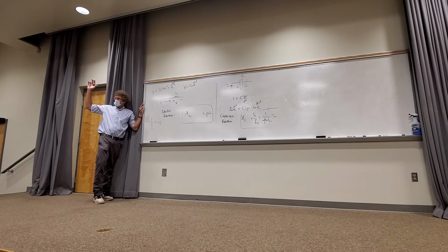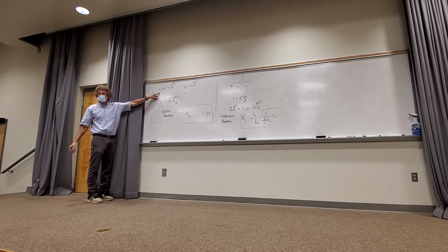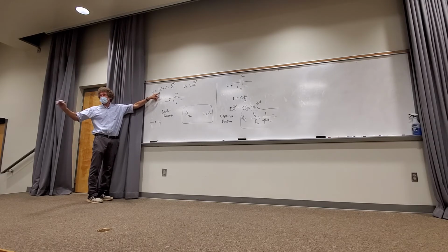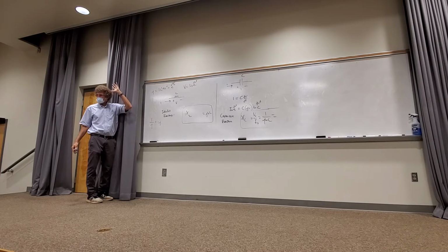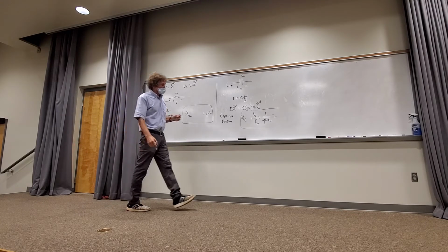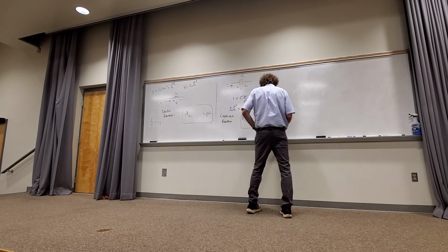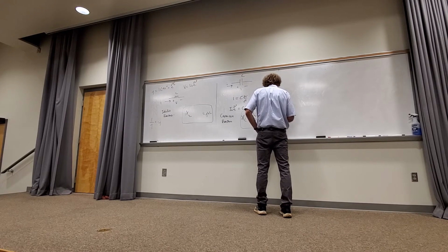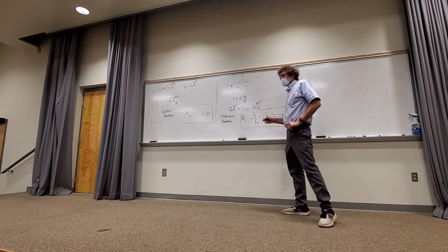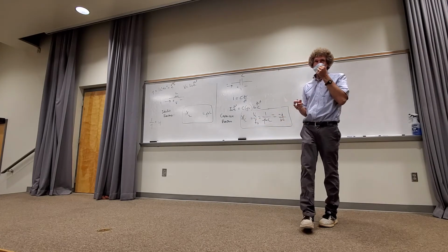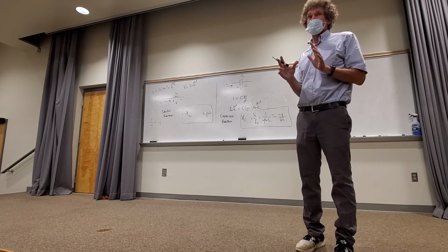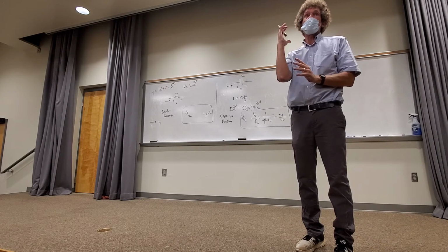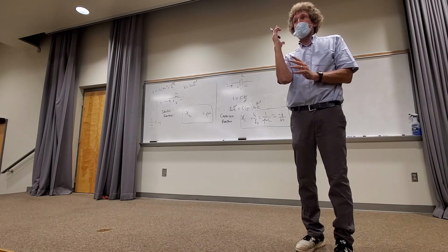Right, class? Just take 1 over 1 at an angle of 90. That's the same thing as 1 at an angle of minus 90, isn't it? The angle inverts. How many see this, class? So I can rewrite this as simply minus j over omega C. What I like to do is talk about the capacitive reactance and the inductive reactance. They're just like resistances, the ratios of voltage to current in an element, only now they have an imaginary context to them.